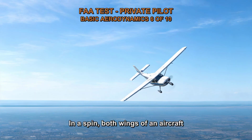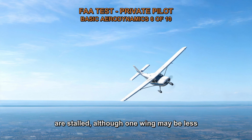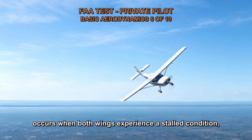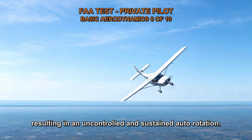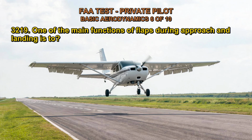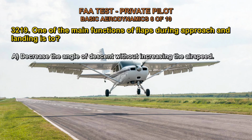In a spin, both wings of an aircraft are stalled, although one wing may be less stalled than the other. It is important to understand that a spin occurs when both wings experience a stalled condition, resulting in an uncontrolled and sustained autorotation.